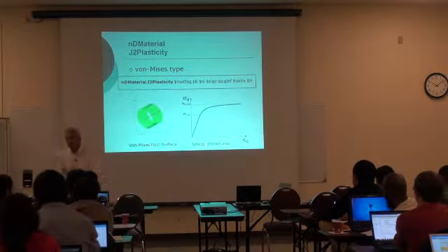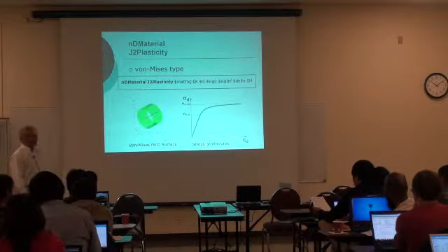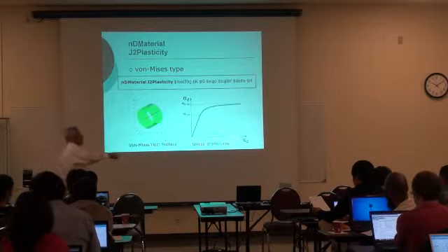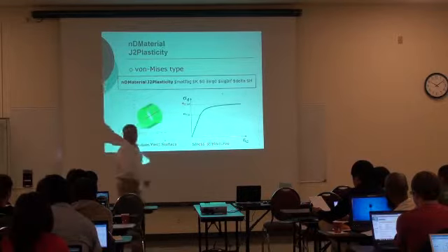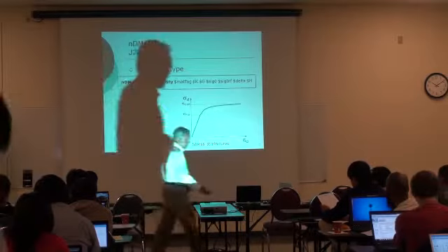And if you're doing seismic events, you will have cyclic incursions. And you want to characterize the nonlinearity in the unload. So in that case, never use a J2 model if you have that situation.